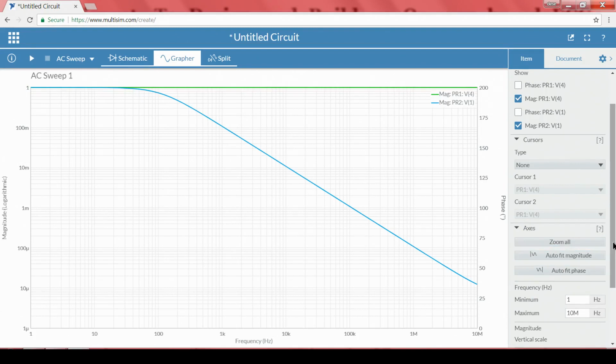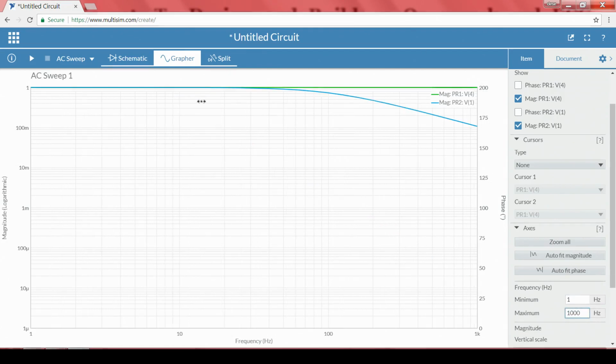In order to do that, I will zoom the frequency domain. I will change these frequency values to somewhere around 1 kilohertz. Now, this is 1 dB, the one below is 1 dB, this is another dB and this is this dB. So, this frequency is somewhere around 700, right, this is 1 and this is 700. So, approximately the 3 dB line.